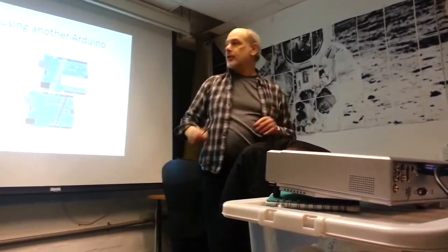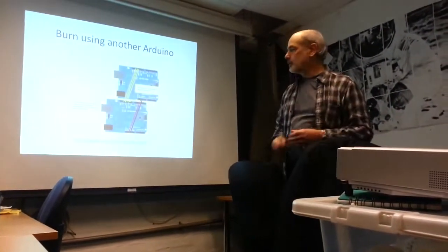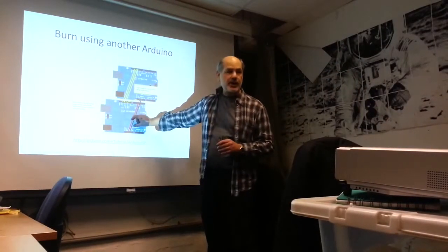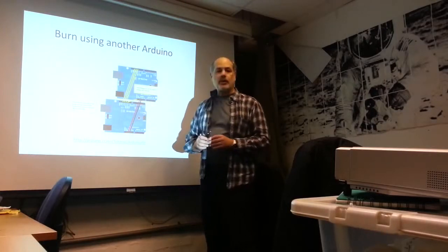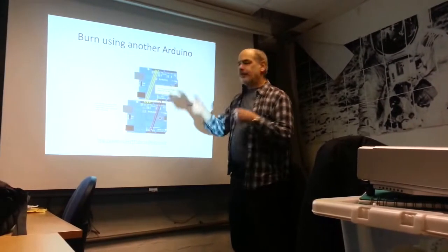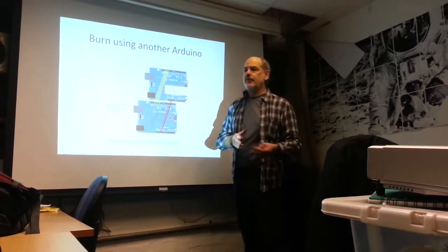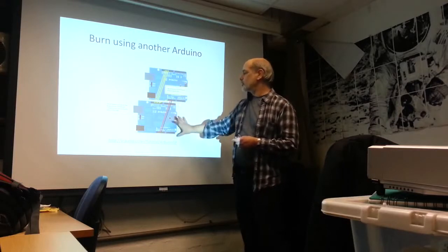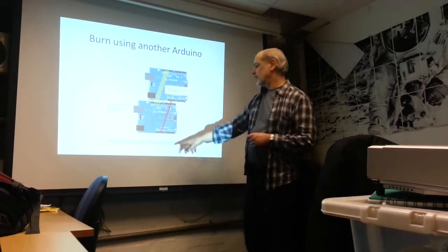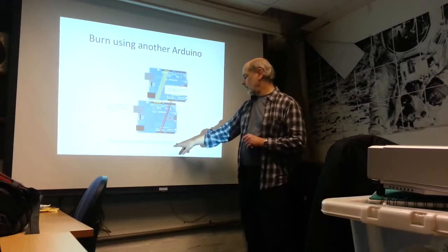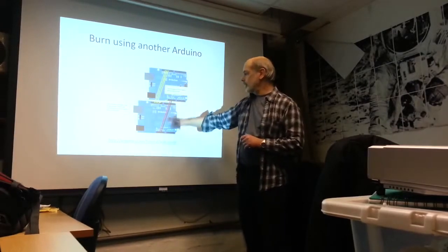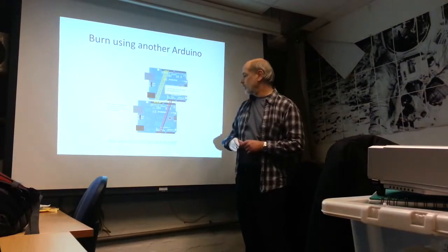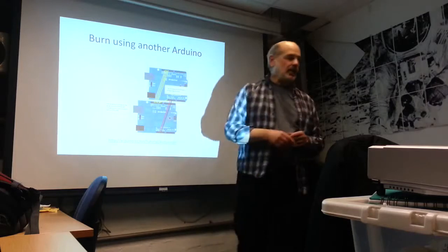Or you can actually use an Arduino board to burn the bootloader. If you need to burn the bootloader, let's say you have to replace the chip and you're using a raw chip, you might want to burn the bootloader. Or if, in the unlikely case, it actually gets damaged somehow and you need to burn it, you can use another Arduino board. And if you look at the Arduino website under Arduino ISP, you'll see this file in a tutorial which explains how to connect up a master to a slave Arduino in order to burn the bootloader.